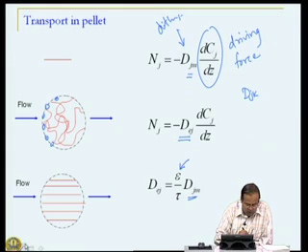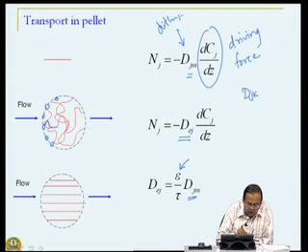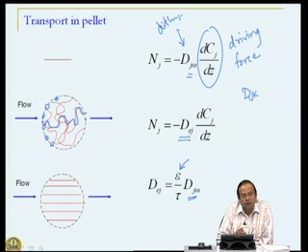For example, inside the catalyst pellet the material may flow changing directions several times, or in other words the path that a gaseous reactant molecule actually travels is much more than the path as represented by this x axis, that is from this end to this end. So, the diffusion rate therefore decreases because it has to now travel a longer path,